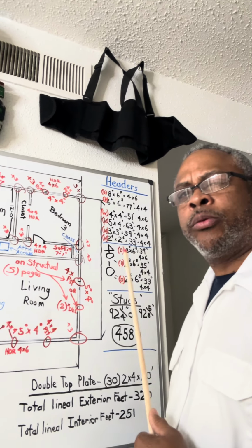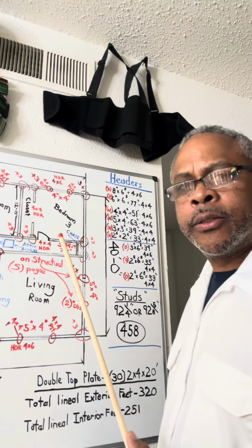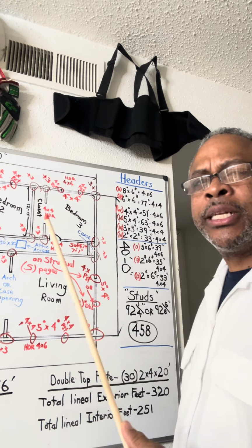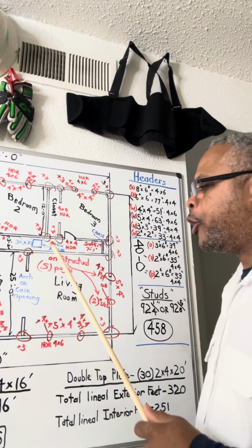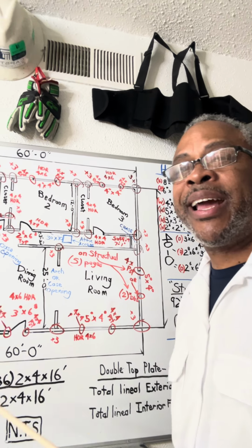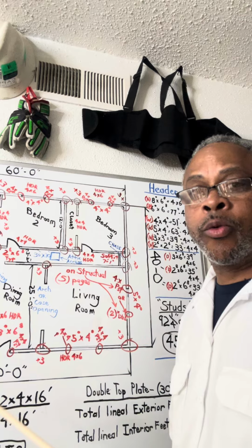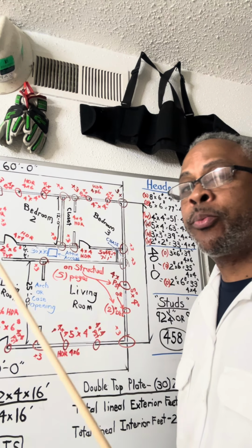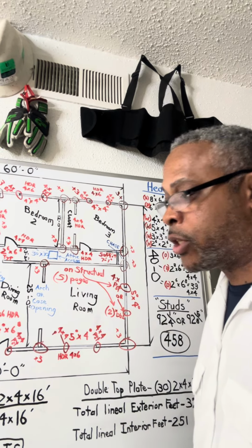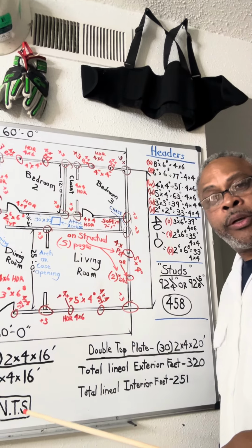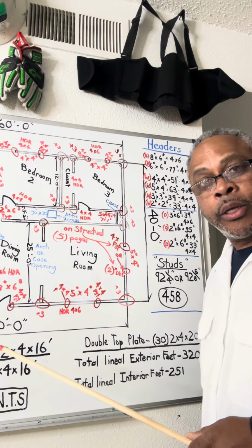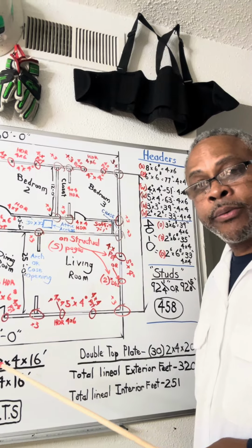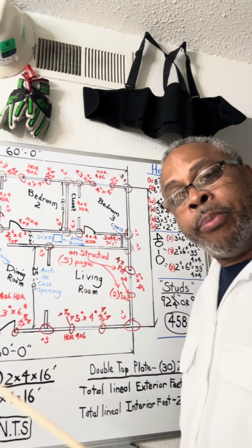It's structurally sound, but it's just different companies and different wood, but it's structurally made to adhere to the structural framing. Your plate material is going to be select number 1. You want a good grade. And like I said, that's usually a green spray painted on the ends of each of the lumber ends for your plate material. Your plate is going to be a really good standard grade. Stud's going to be number 2 or better. Your header stock is number 2 or better.